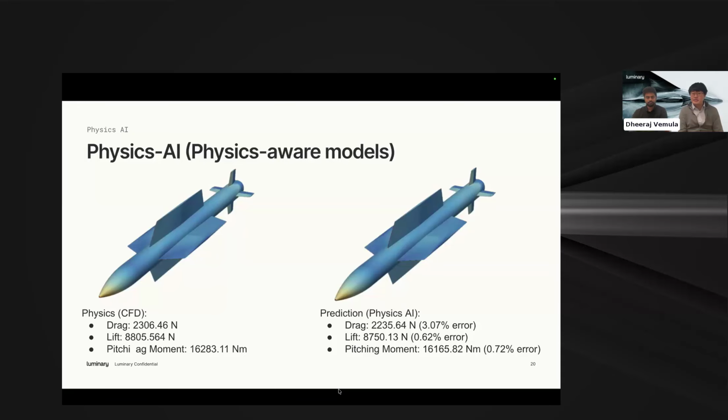And one thing I want to point out is this is not just a normal surrogate model or a normal neural net. These are leveraging state-of-the-art transformer-based models. These models were based on inspiration from existing LLMs, where you are creating these geometry tokens to make inferences based on how features, for example how a fin, would lead to some flow structure on the surface. Once you infer on these tokens, you get to see the whole full-field surface distribution. Here you can see an example of the pressures on the surface, and we compare them to what we see in CFD.